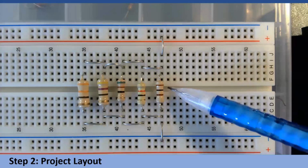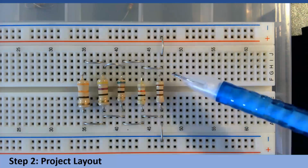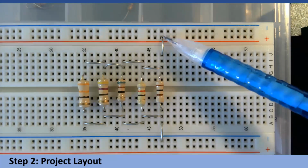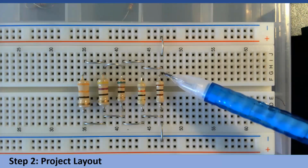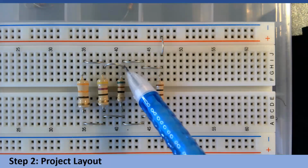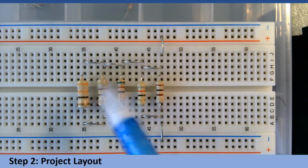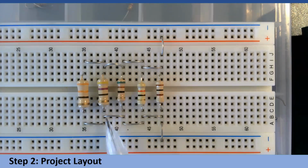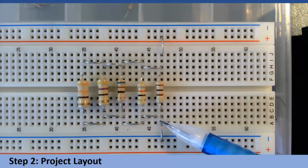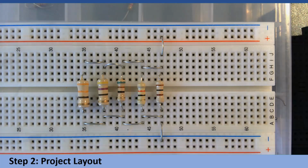The moat separates the two ends of our resistors, so we must connect them all together to make a parallel circuit. I have a jumper for my positive power rail feeding this row. It will carry on to this row through the jumper, through this row to the next jumper, through this row to the next jumper, and so on until the last resistor. I've done the same on the other side, and another jumper that goes from the first resistor, reading from right to left, through the power rail on the negative side.